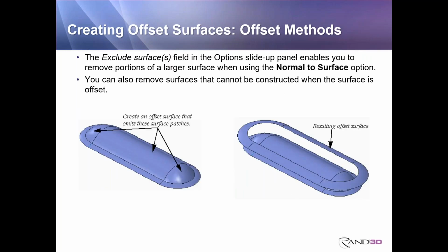Now, when we're doing this standard offset, Creo is going to have you pick one quilt. In my example on the left, this quilt that I'm selecting happens to have about 8 surfaces inside of it. I actually don't want to offset the entire quilt. What we're going to notice when we go to pick the geometry that we want to offset is that you do have to start by picking the entire quilt.